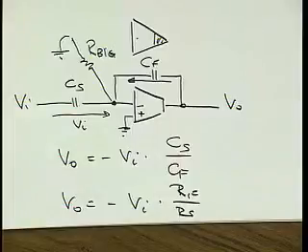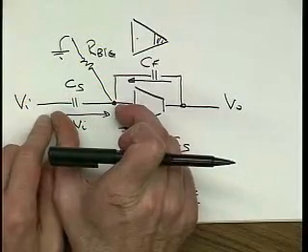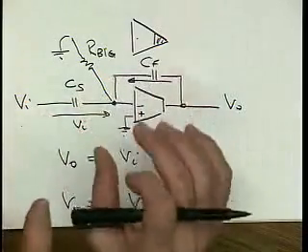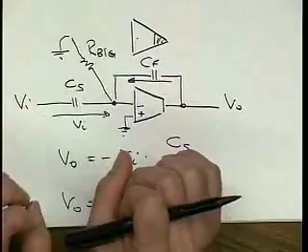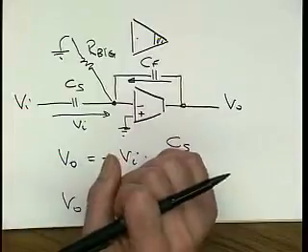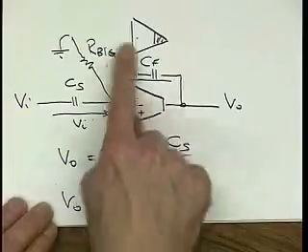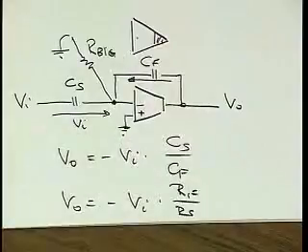So what really works and what is used in practice is that we use switches to temporarily short circuit these capacitors, to put the right voltage across them. That introduces the notion that sometimes our circuit is unusable because we are, let's say, deleting the charge stored on CF. And one way to deal with that would be to do that only, let's say, when the circuit is powered up or something like that.